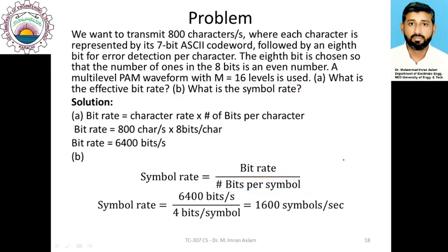So this was a basic introduction to how an analog signal is transformed to a digital signal by PCM, which includes several steps. The first step is sampling, and then we pass it to quantization, so that we transform the sampled values to predefined quantization levels.